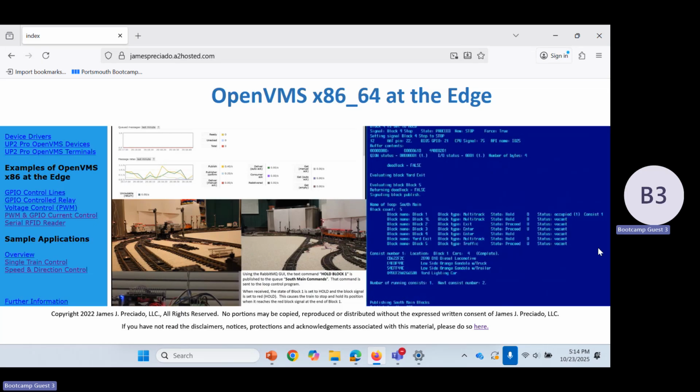That's a little too much work. So I'm probably just going to have it complete, have an internal timer routine that goes back and just sets it off. If this ever comes to the point where other people want it, then I probably have to go back and fix it. And I really got to figure out a way to get to that hidden piece of data, that hidden PCI device that Intel is hiding, because that's how I'm going to be able to do GPIO input. I can do input now, but it's synchronous. That's how I'm going to be able to do input and interrupt when the signal changes state.